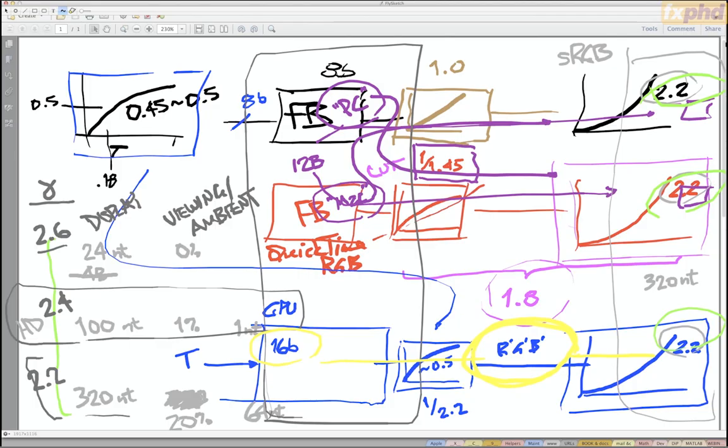I mean, even though we've got HDMI and high color and 12-bit and 16-bit and so on, this is still predominantly 8 bits in the real world. And it's only this power function behavior that lets us use that 8-bit channel, and that's a big deal. Okay, Peter, I hope that addresses your question about historical leftovers and native characteristic of displays.